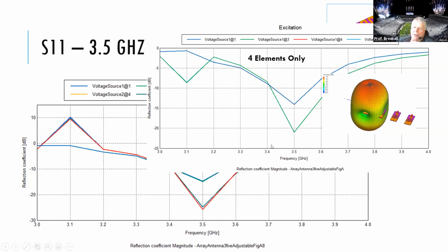Yeah, I also have never seen a reflection coefficient go up like that. It'd be interesting to look at the actual impedance. The only thing I could think is that sometimes in arrays you can get basically a negative impedance, a negative real part, and it means instead of power coming out of the antenna, power is going back in.